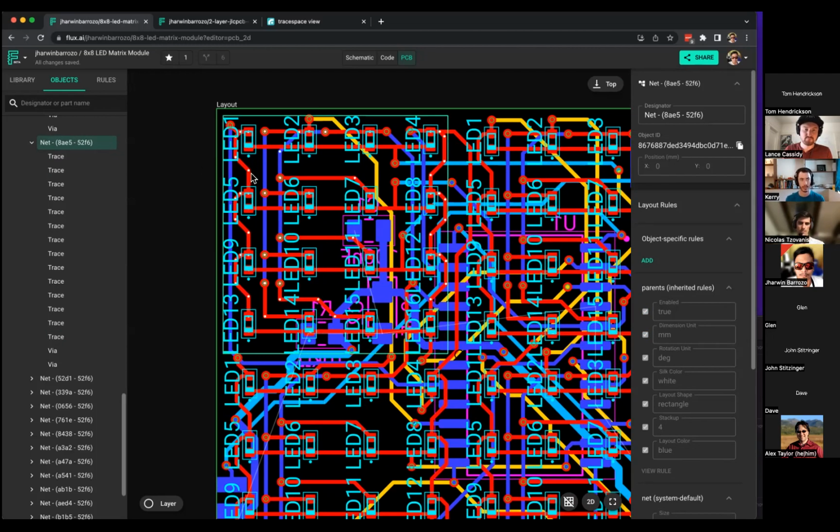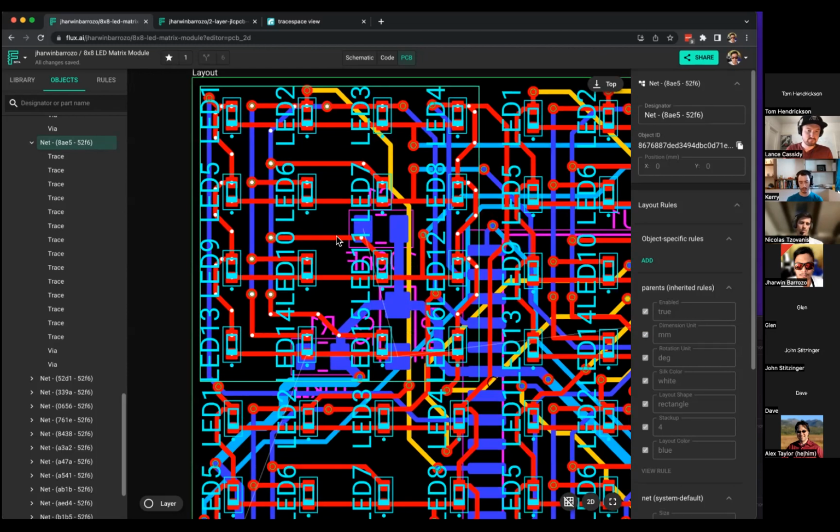For example, this one here, there's a component blocking the way for some other traces in here. There will be a shortcut you can press to drill down, similar to Figma. If you are aware of Figma, there's a shortcut you could press on your keyboard, and eventually your mouse is inside that folder that blocks everything. So you could select this trace in here.